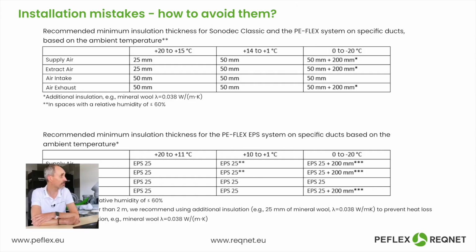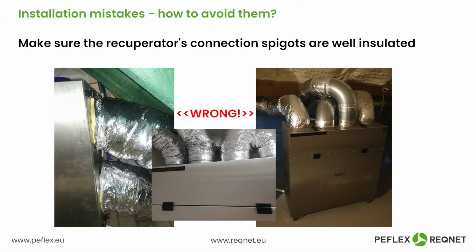When it comes to supply, exhaust, and the exhaust vent, it's to protect against condensation. For supply and exhaust, we need to protect against heat loss during transfer, and for the exhaust vent, we protect against water condensing inside the duct. If you can see the insulation wool on flexible ducts, then 99.9% of the time that wool will get soaked, and that duct will have to be thrown away.